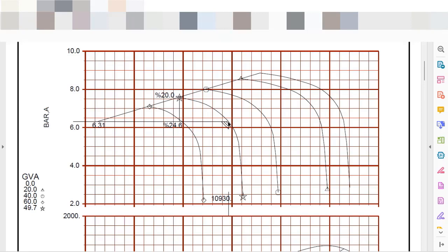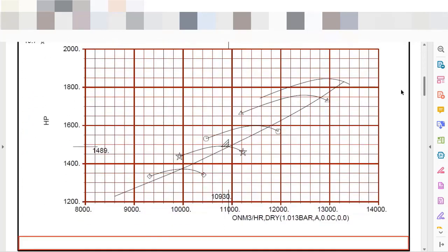If I want to have a lower flow in my equipment, I will change the guide vane opening, for instance to 60, and I will operate in this range here, and I can verify what the new conditions are in terms of performance. So here, based on the opening of the guide vane and the flow of the fluids in the equipment, I have a requirement of power.